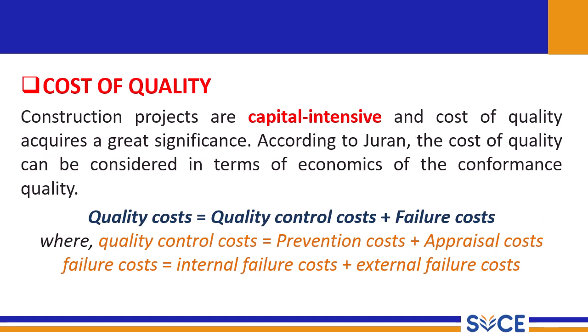Cost of quality. Construction projects are capital intensive, and cost of quality acquires great significance. According to Juran, the cost of quality is considered in terms of the economics of conformance. The quality cost is equal to quality control cost plus failure cost, whereas quality control cost is equal to prevention cost plus appraisal cost, and the failure cost is equal to internal failure plus external failure cost. So this is a basic expression for quality cost.